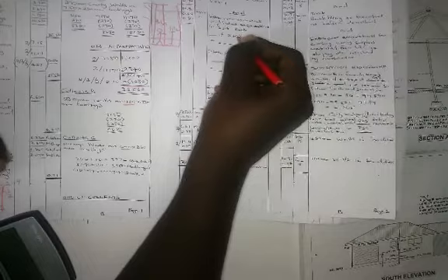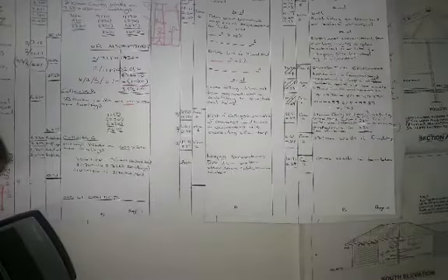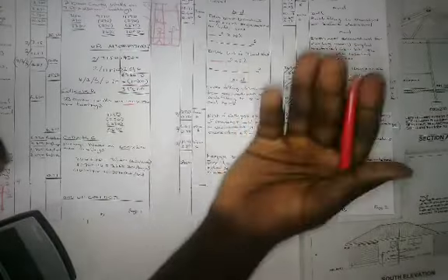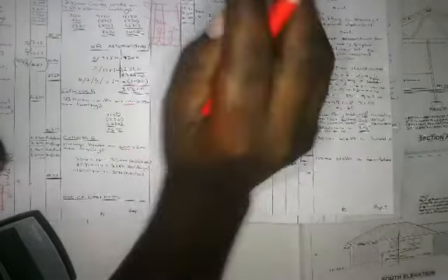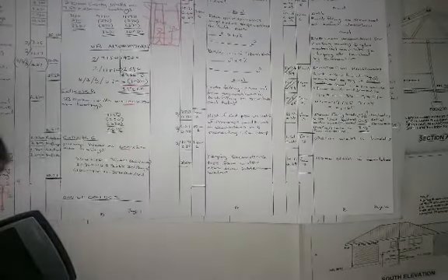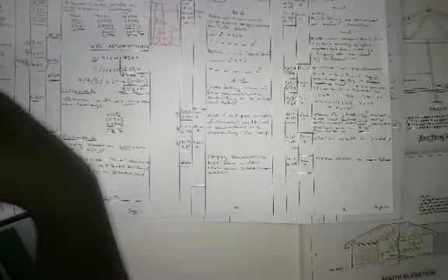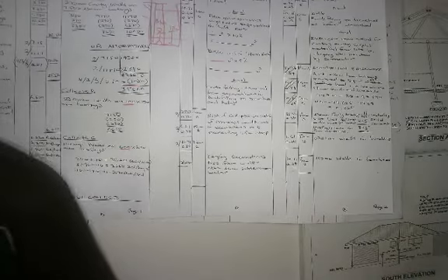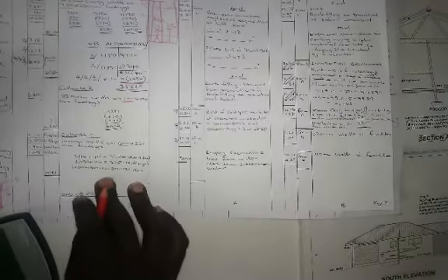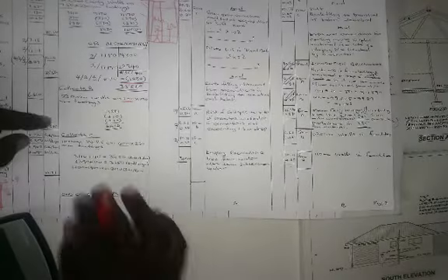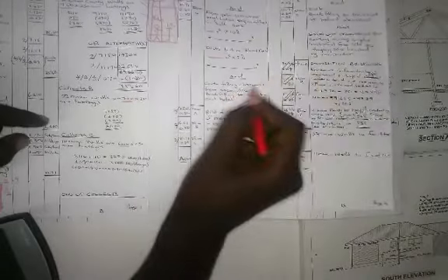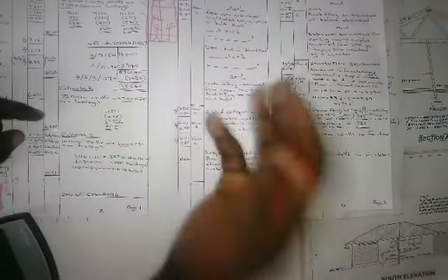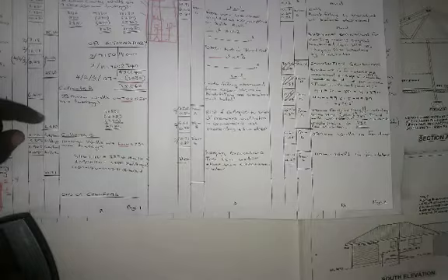So you can calculate all of this out, get a cubic meter quantity and put it here, multiply it with the calculator to get your percentage and put the answer there. That is for your rock excavation. This information will be taken and put into what we call a bill of quantities for tendering purposes. That will be given to your contracted price.